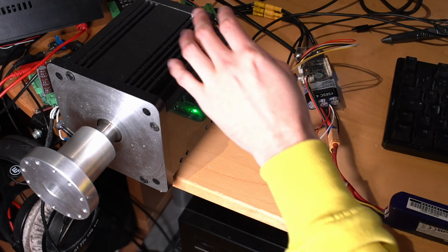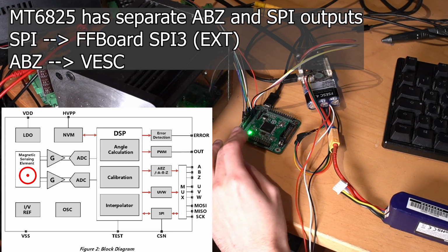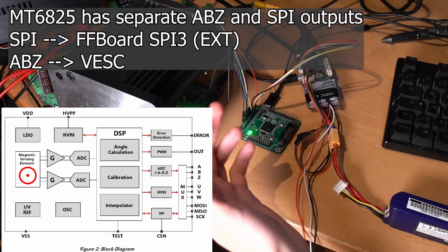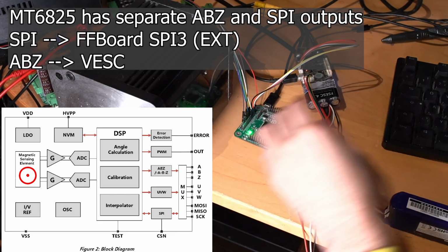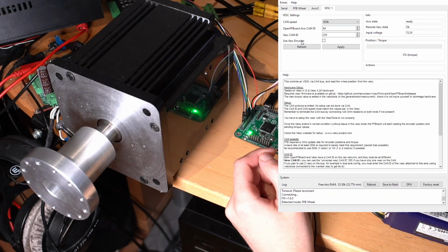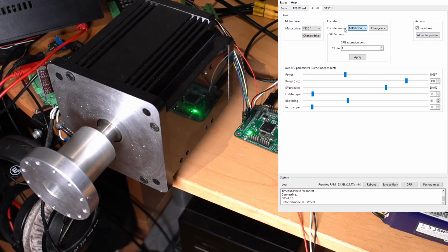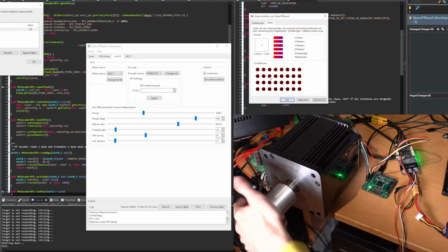I have now connected the MT encoder on the servo motor via SPI to the FFBoard and with its ABN output to the VESC. This is basically just like having two completely separate encoders, one connected to the FFBoard and one to the VESC. And the use VESC encoder checkbox is not checked right now. And as the encoder source, not the VESC is used, but we have selected the MT encoder via SPI3. And it is still completely working normally.